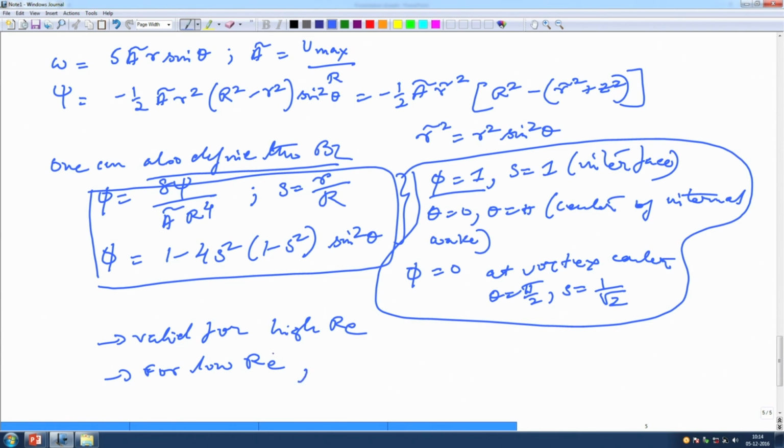there is another solution that is given by Hadamard, which is also a quasi-steady solution. There also the inertial terms in the liquid and the gas are neglected because it is a low Reynolds number solution, and the linear equations are solved by separation of variables, and the Hill spherical vortex even applies there. Got it?